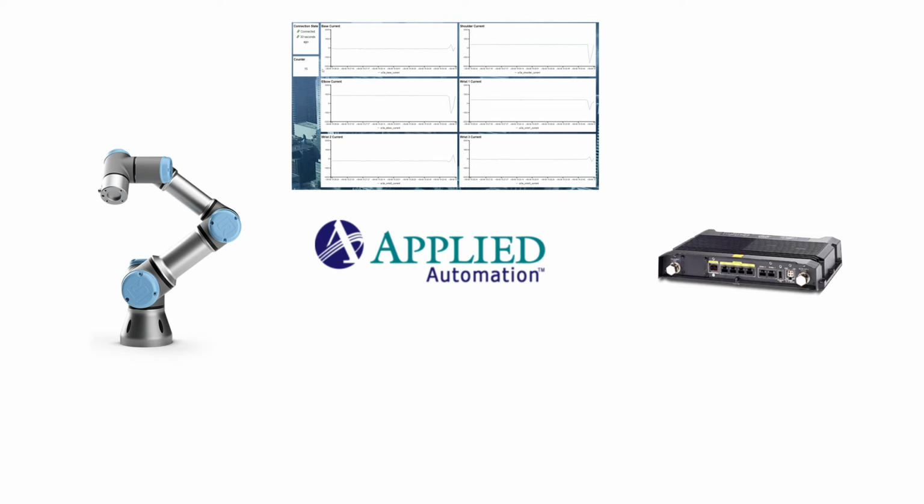This video will focus purely on configuring the gateway to pull the data that we want from the UR3e. To keep it simple, the data that we're going to pull from the UR will simply be joint currents and a general purpose register. This process will apply to any data that you'd like to pull from the UR. Behind the scenes, I've already configured the UR and the Telit Gateway's local area connection to be on the same subnet. So we should easily be able to step into configuring the gateway.